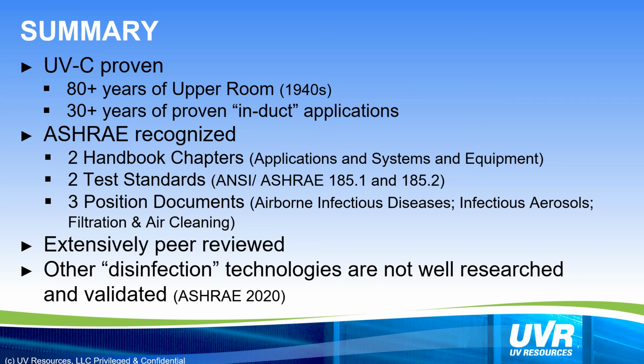UV has been around for 80+ years in upper room applications and more than 30 years in airstream and in-duct applications. ASHRAE devotes 2 handbook chapters that discuss the benefits of UVC. There are also 2 ASHRAE test standards covering UVC. 185.1 tests airborne or on-the-fly disinfection, and 185.2 tests coil and surface performance. 3 ASHRAE position documents also support this technology. And remember, UVGI HVAC technology is extensively peer-reviewed. However, many other air treatment products are not well validated, independently tested, or researched.